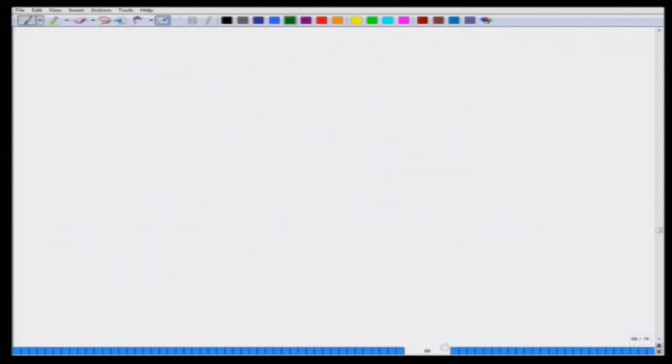So, now what do I have? I have the OFDM samples with the cyclic prefix. So, I have the samples x0, x1 up to x of n minus 1, to which I have added the cyclic prefix, x of n minus 1 up to x of n minus L bar. This is my prefix.